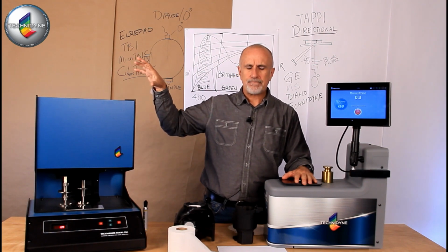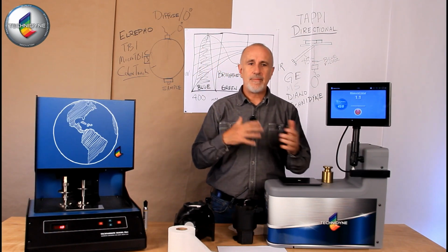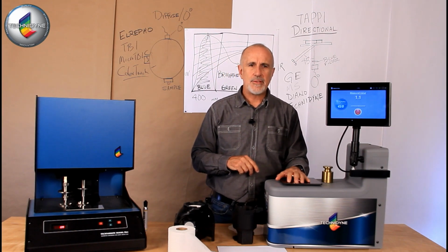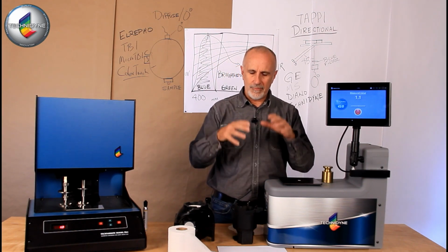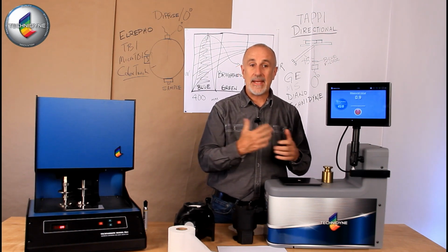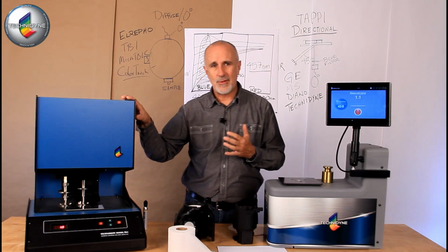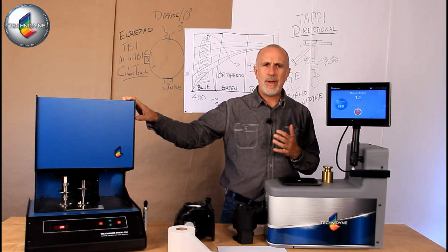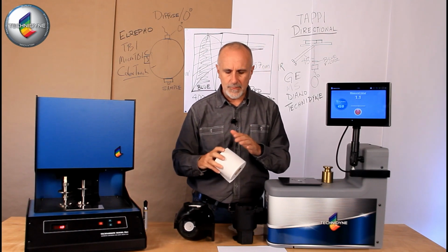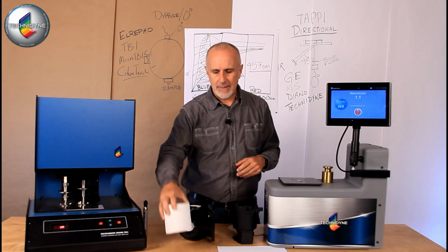In Asia, well, certainly in Japan for a period of time, they had a directional method. They've now modified that, and they're moving more towards the diffuse geometry with that. So it varies wherever you are in the world, but as a rule of thumb, you can assume that in the U.S. it's the TAPPI directional method, exceptions being the newsprint industry that globally standardized on the ISO method many years ago. Most tissue manufacturers are going to go with the ISO method because of some translucency issues that this does a better job of handling than the TAPPI method does.